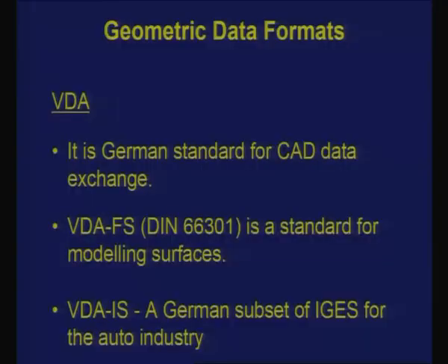VDA is another geometric data exchange standard. This is actually a national standard, a German standard for CAD data exchange. There are 2 options. One is used for surfaces, and we know that most of the German standards have a DIN number. So, VDAFS has DIN number 66301, which is used for surfaces.